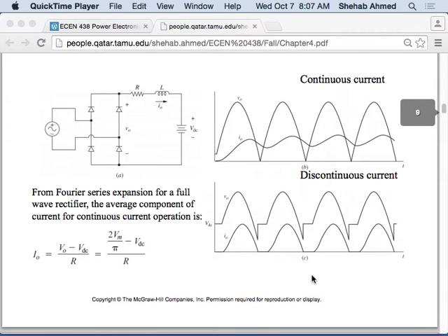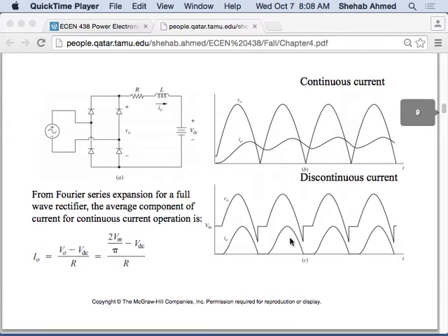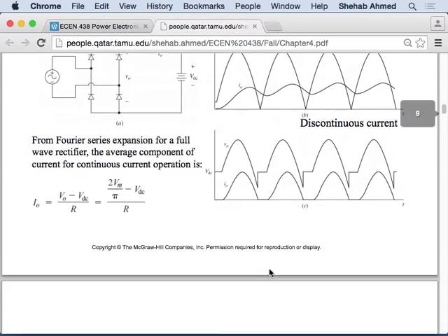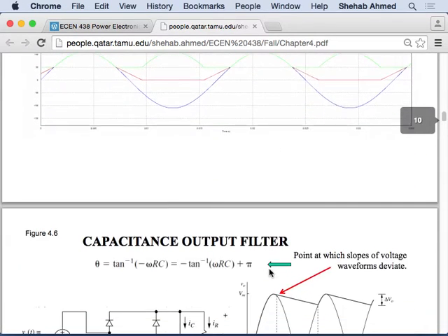The RL source, we did that for the case of low DC voltage and or large inductor case. So we said the low DC voltage case with a reasonably large inductance, and then we did the case where we maintained the DC voltage and decreased the inductance, for example. So we talked about the continuous and discontinuous case here as well. From a waveform perspective, we did not touch equations.